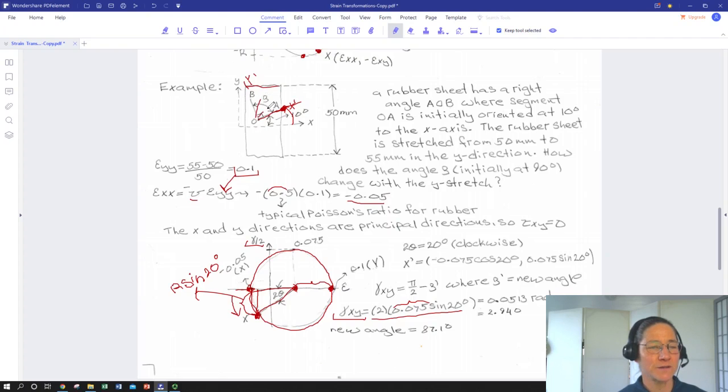So we invoked the fundamental definition of shear strain and then represented that as simply a vertical axis, or a gamma over 2 axis coordinate on the Mohr circle. So it's a lot easier than trying to envision how much this line is going to come over and come up, or trying to calculate some displacement of those 2 coordinates. We just have to basically get the corresponding shear that goes with our x prime.